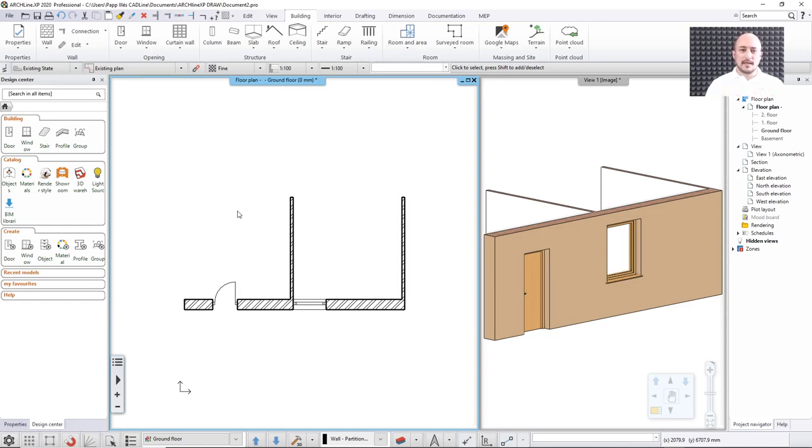Now this is the cool thing in it, that I don't have to make manual copies of this drawing and handle them in separate files or even in separate windows. Everything is inside this one logically organized ground floor plan, which I already have. I only need to decide what to do with these items, whether I would like to make them removed or I would like to handle the separate phases or not. So this is actually just a free choice.